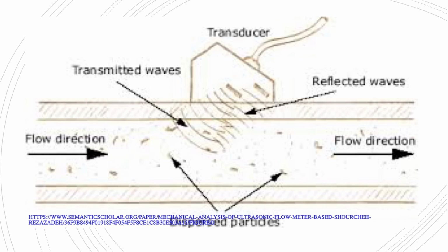The transducer generates an ultrasonic signal that passes through the pipe wall into the flowing liquid. The transmitter then converts the difference between its output and input frequencies into electronic pulses. These pulses are then processed and scaled into a measurement of flow.